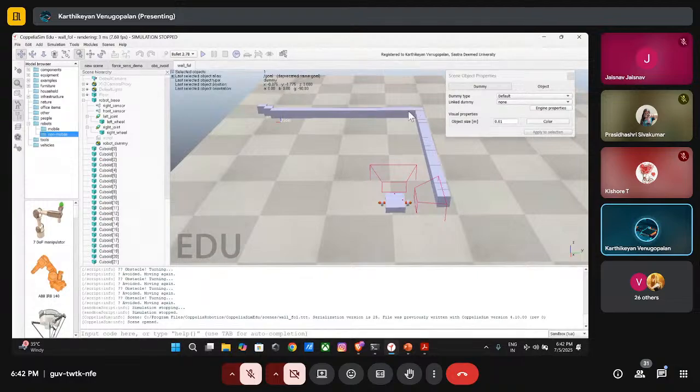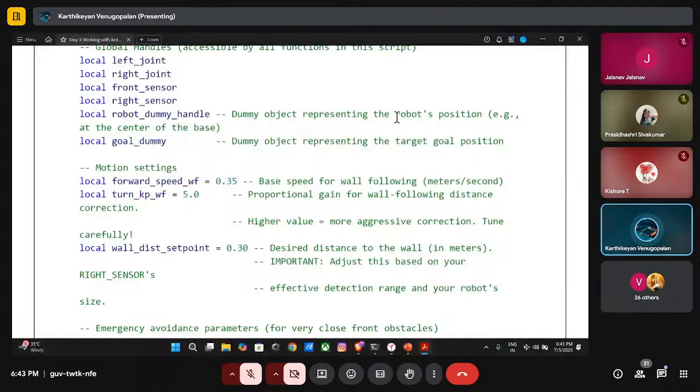In this kind of sharp turns, the front sensor is going to be an important thing. Once the front sensor is detected, I want to make a sharp turn. And the third thing is the emergency case. While I am keeping some duration initially, I can't say there isn't anything in my way. So I am making sure that if any object is closer than some defined distance, I have to make an emergency backward pull for that particular bot, and then follow the wall again.